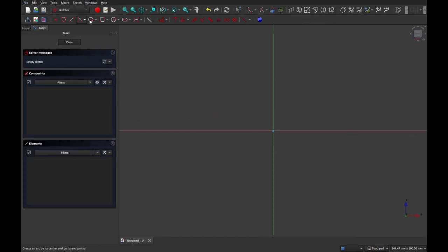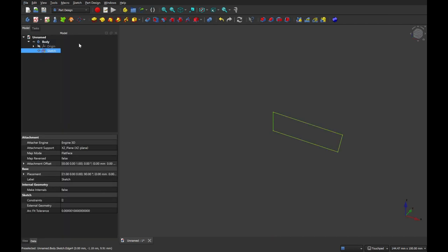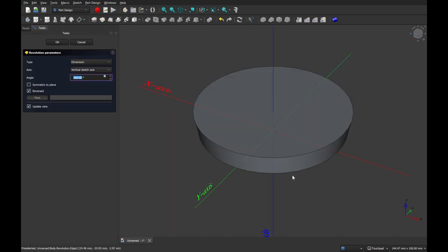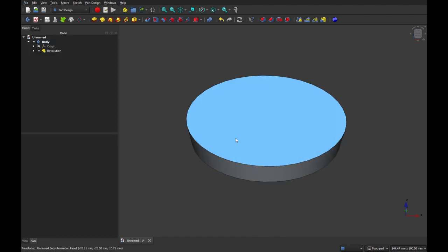So initially we could, now I'm not going to bother dimensioning this, I'll just create it as we go. Right, so as a revolve, you would dimension this top one and the bottom one and the thickness, and that'll give you the shape of the conical section. But let's say we've got that now. Do a revolve, and there's your basic shape of your plug. So, okay.